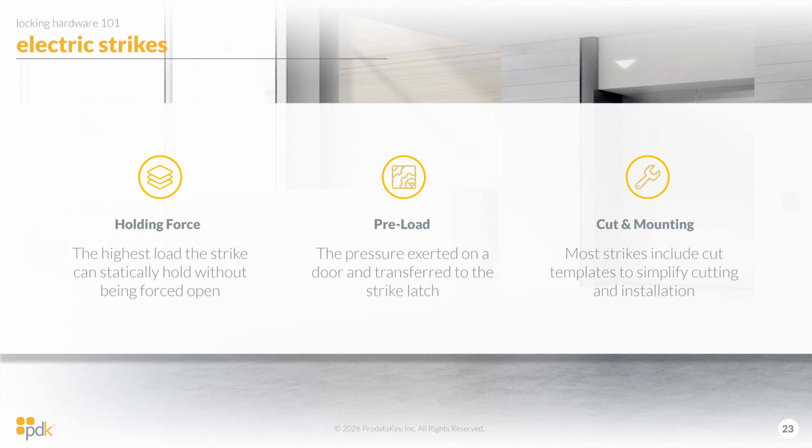Okay, so with strikes, you have a few different forces, not nearly as many as mag locks, but you're going to have a holding force, which is how much it can hold. And then you have the static load of the door being exerted on the strike that you'll want to account for as well. Fortunately, all strikes have a cutting template that allows you to cut into the door frame.